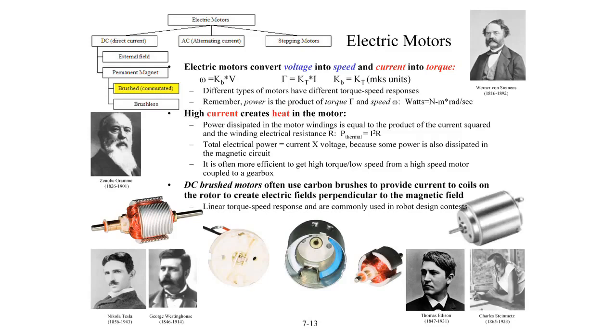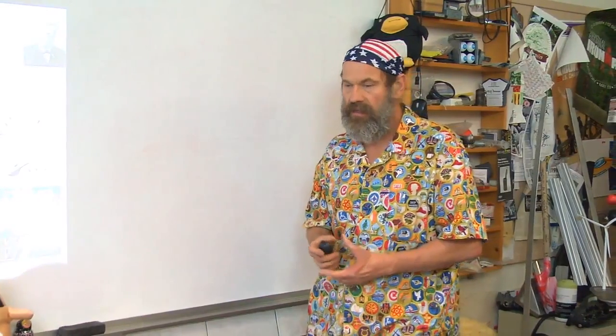Where else are these actuators used? Well, if these weren't used everywhere they are, we would have no cell phones. Why? Because the chips inside this cell phone are made in the semiconductor process, which uses a machine called a wafer stepper. Wafer steppers use these little fine motion positioning stages that position the silicon wafers under the lens stack, which then imprints the pattern that makes that wonderful magic circuitry that gives us the cell phones.